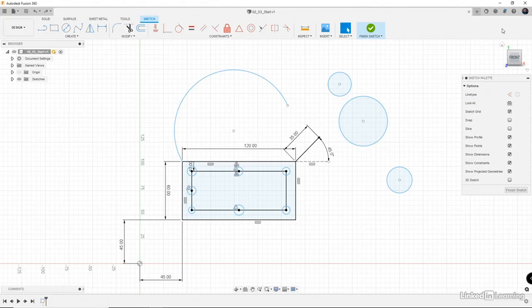Now that we've gone ahead and talked about both dimensions and constraints, let's talk a little bit about the editing of them. So if you come down here, you can see any of these sketches, and you've seen me update some of these before, but just to clarify, you can take any of these dimensions and simply by double clicking, you can update these values. So you could change this to, for instance, 40 millimeters, and you could also update the angles.